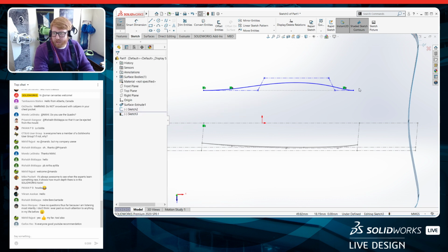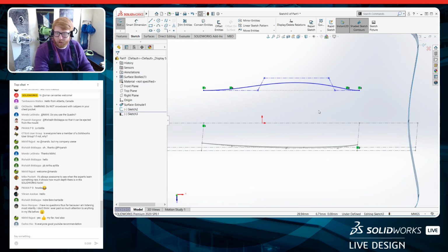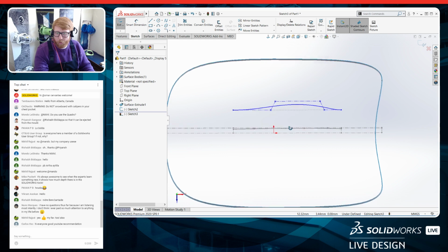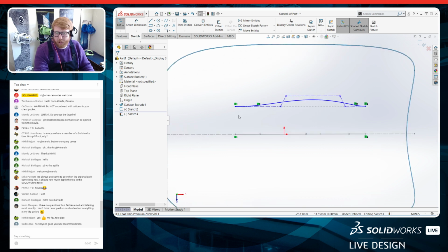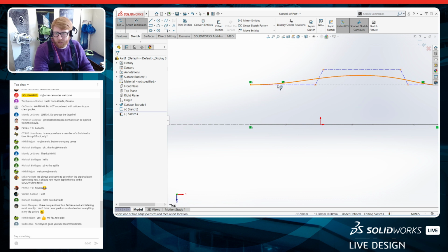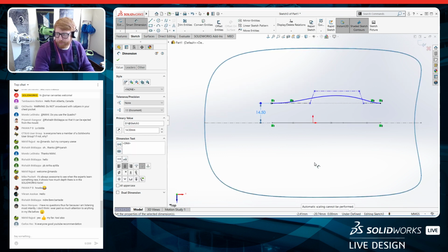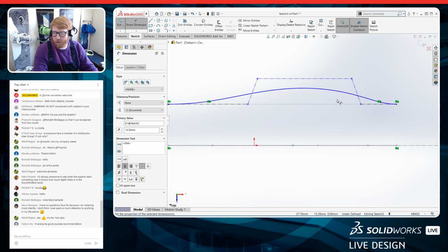All right, so now I can say there's vertical here and vertical here. All right, and now I know the width of this thing as well. The width in the beginning and the end is going to be 29, right? So what I'll actually do is say 29 divided by 2. Boom. I've already made them collinear.